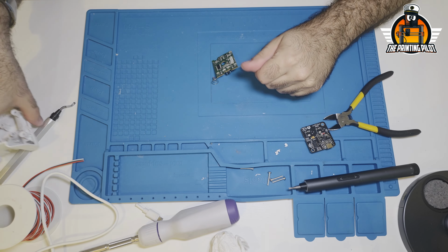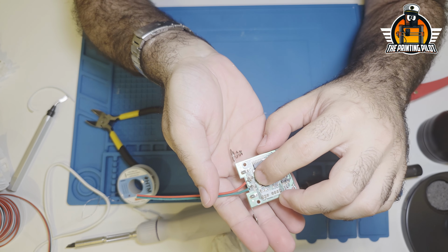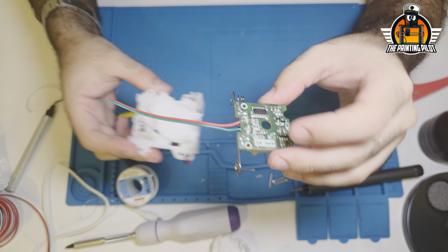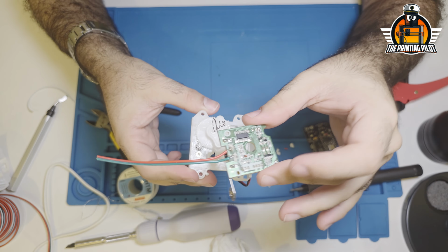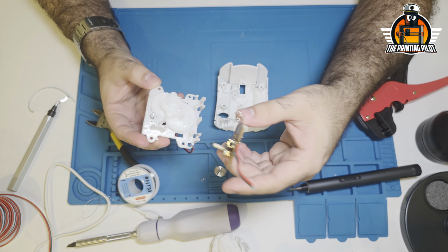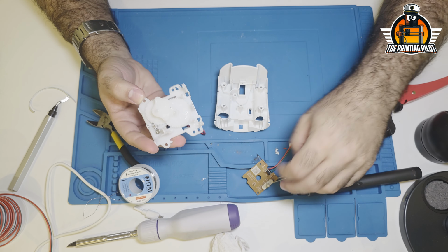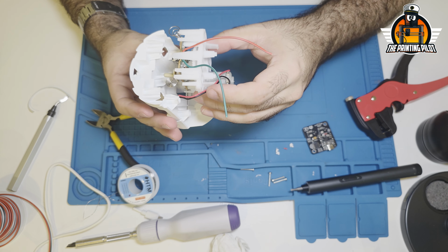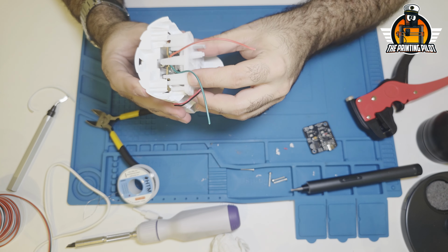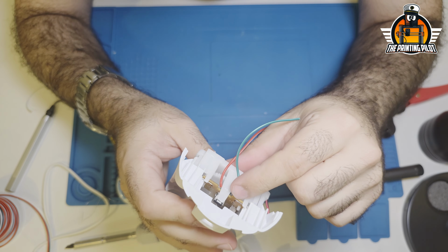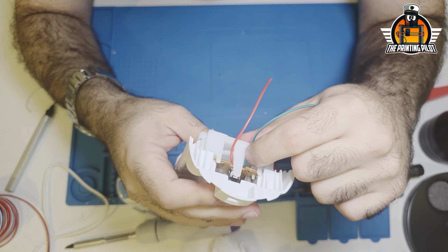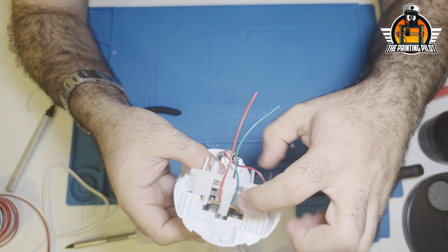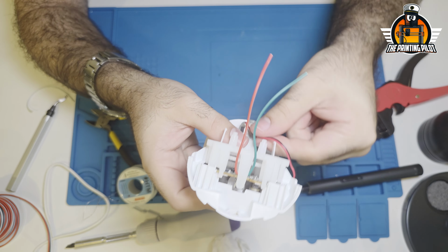So let's now take a cable. And now after soldering those 2 wires, we can start assembling, putting this PCB back in, and we are done with this sub-assembly. So the PCB goes in again, and then the entire motor with the gear and PCB assembly is going to be pressed back into position here. Now make sure that your cables are moving below this portion and up here, and not coming up from this side, because then it will interfere with the cable and with us closing everything.